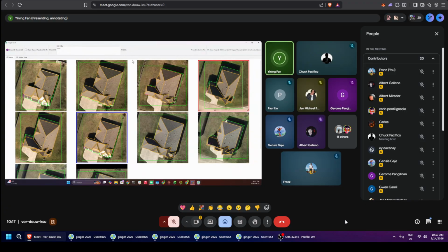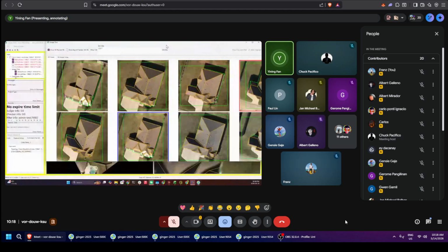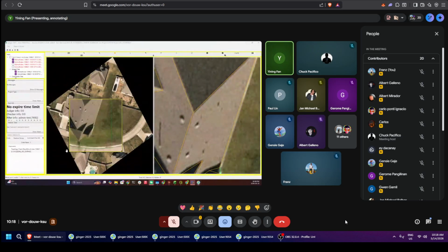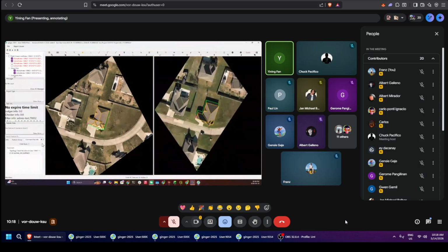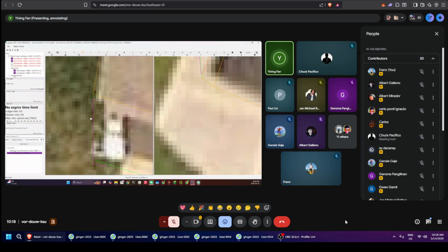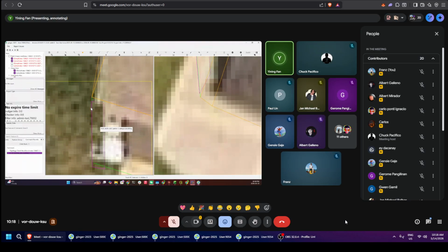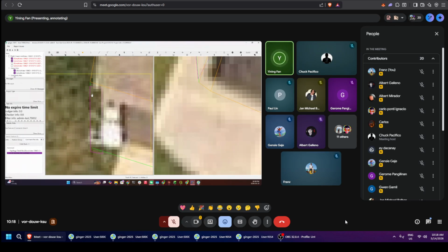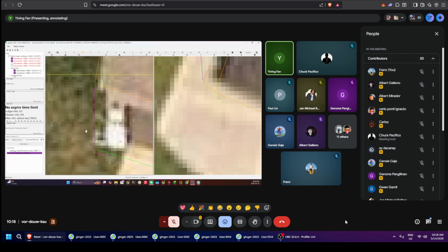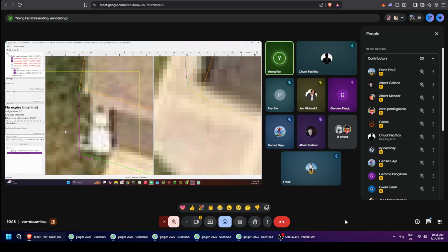This is not the actual final report. Once you hit Alt R, it asks me to fix the topology error. Let's see what kind of topology error it is. Okay, this is a pretty common one, just as I mentioned. Right here, you see this particular facade, this particular corner is a rectangle. It's not really attached to the sidewall anymore. That's why it says illegal ISO surface.